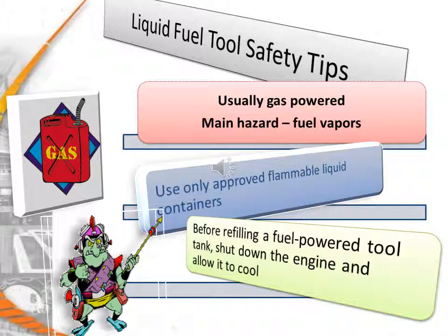Liquid fuel safety tips. Usually gas-powered tools have their main hazard in fuel vapors. Use only approved flammable liquid containers, and before refueling a fuel-powered tool, shut down the engine to allow it to cool.